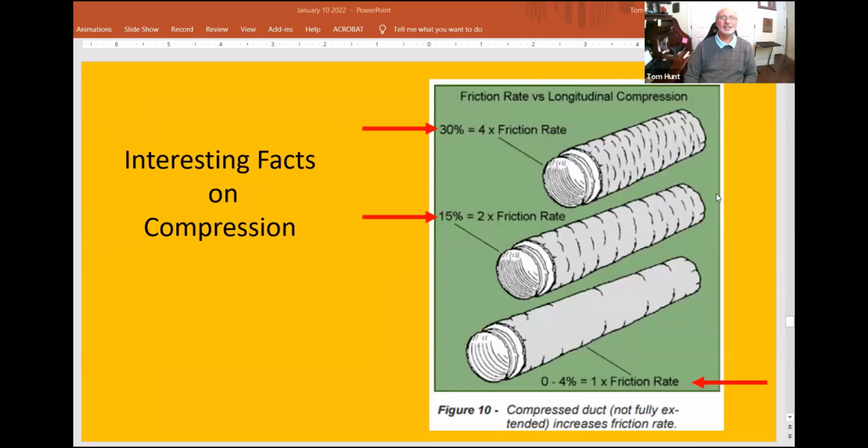Here's the thing you mentioned a while ago. We were talking about how if you do flex, you've got to do it differently than metal. You want to talk about the compression problem that you have with flex duct? Absolutely. In fact, these numbers that we use when we're out in the field, we use their ductilator. I actually have it. It's their ductilator, and it has the compression ratio, the 80I one. That's it right there. And it starts at 4%. They're not even allowing an actual reading until you run it to that bottom one at 4%. If you're running anywhere else, you're losing much.